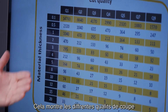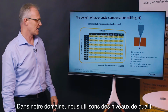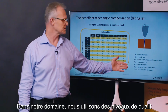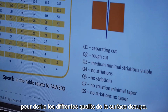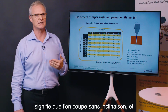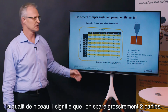And just to show the benefit of this, we have a data table of stainless steel. This shows the different cutting qualities and the speed at different material thicknesses. Typical for the water jet business is that we use quality levels for describing different quality of the cut surface. The quality level number 9 means that we are cutting without any taper, and quality number 1 means just a separating cut.